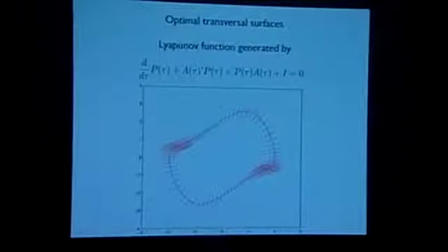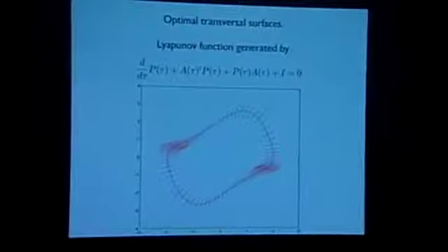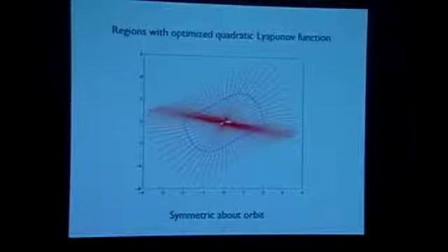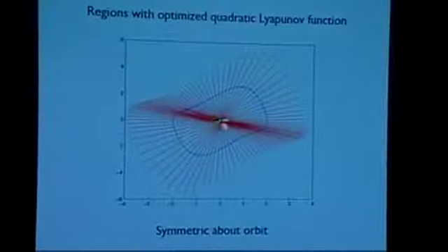It actually helps a lot to do your optimization both over the Lagrange multipliers, which verify stability, and over the Lyapunov function itself. So whilst this quadratic Lyapunov function is great for the linear theory, it's not optimal for regional analysis. So we're going to do an optimization in that as well, and that can also be done very efficiently. I'm searching here over quadratic Lyapunov functions in quite a general form, and this is the region I get now. It's pushed in right to the middle. There's a couple of gaps missing there just because of the degrees of the polynomials I was searching over. And you see that it's pushed out into free space about this much.